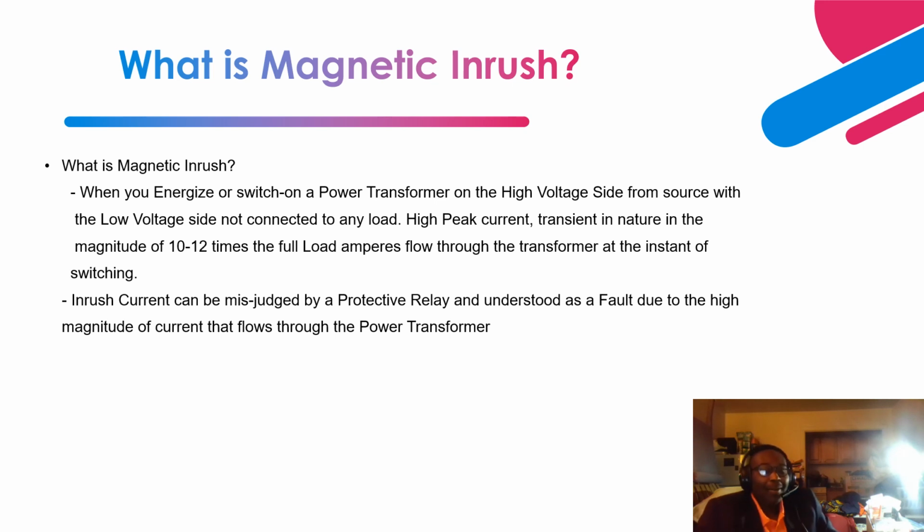Okay, so now let's move on to the next slide, and we'll talk about what magnetic inrush is and the definition of magnetic inrush during energization of a power transformer. As you know, if you energize a power transformer, the high voltage side is connected to the source. So once you apply that voltage to the high voltage side, the low voltage side is open circuited. It's not connected to any load.